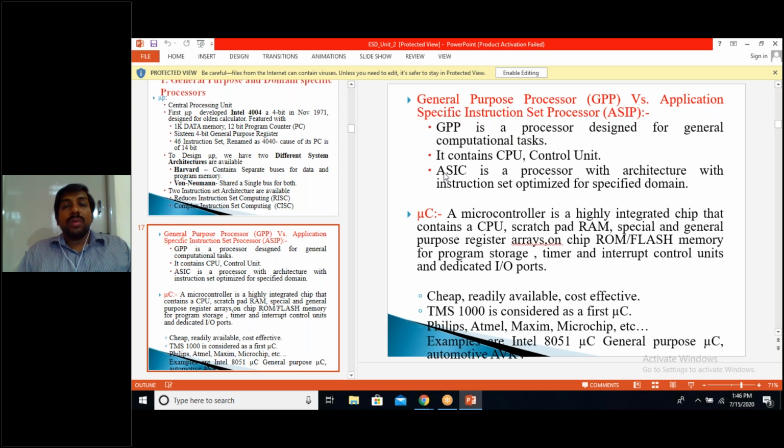So for that, you can design your own hardware processor, that is called ASIC. ASIC stands for application specific integrated circuit. Based on the application, its internal hardware is designed. So for that, you have to create your own IC from the manufacturer. So it is an optimized design, optimized instruction set. It is your own processor. So based upon the vendor, if Samsung is creating its own washing machines, it will create some separate ASICs for all its washing machines.